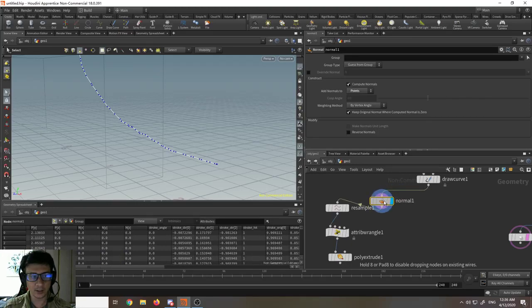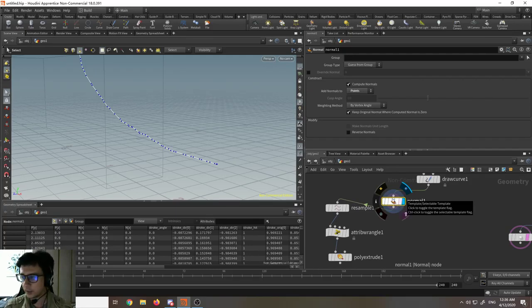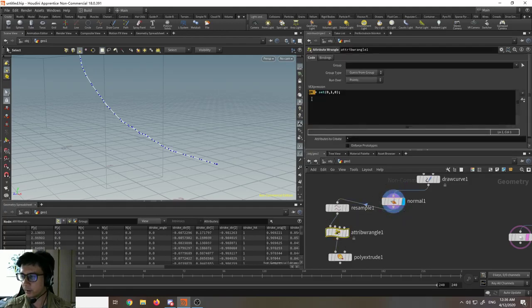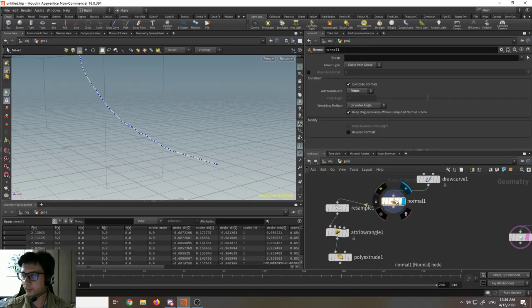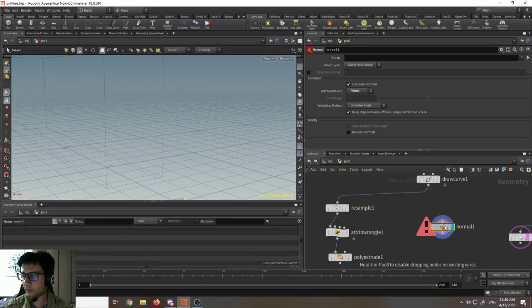So n needs to be capital N, because there is a difference between the lowercase and the capital. Houdini won't know that it's the normal you're looking for. But N stands for normal in Houdini. And in this case, it's not that I'm creating a new one. N is something that any object in Houdini can have. So what it's just doing is creating a normal map.